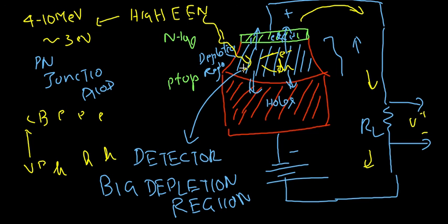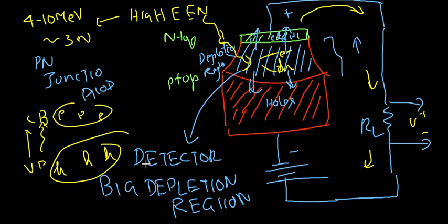When the radiation falls on it and it absorbs the radiation, because the energy is very high, it will facilitate electrons jumping from the valence band to the conduction band. Very little energy is required for an electron to jump, but the radiation energy is 1000 times larger, so more electrons jump from valence band to conduction band, creating abundant electron hole pairs.